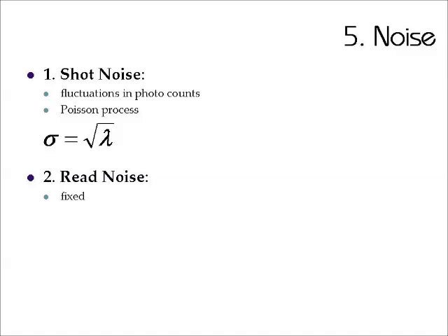And then finally, we have noise in the digital system. There are a variety of different types of noise. Two I want to focus on now are perhaps the most important. Firstly, shot noise, which is the random variation in the arrival of photons at your sensor. That can be modelled using a Gaussian distribution. Now remember, these are integer data because we're counting individual photons, so you can model this with a Poisson process.